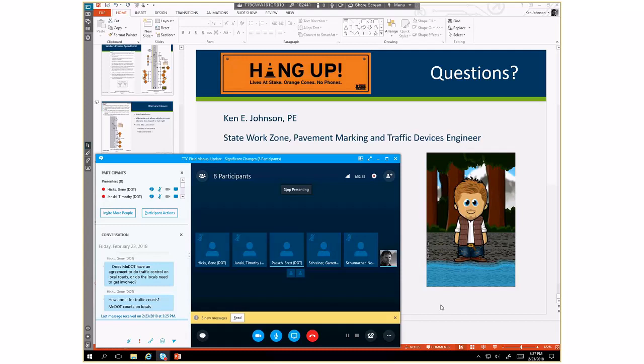Ken, this is Brett here in District 7. Hey Brett, how you doing? Good. Quick question. I would bet that all our sign shops or maintenance aren't currently bringing detectable edges with them when they do sign installations on stands. Yep. Is there a recommended product? Are other districts fabricating their own, or is there an off-the-shelf product they can look at? To my knowledge, there is not an off-the-shelf product for this. Now the portable, because generally MnDOT we might use Z stands, or we might end up using the steel tube NCHRP 350 crash tested device that we have on our website.